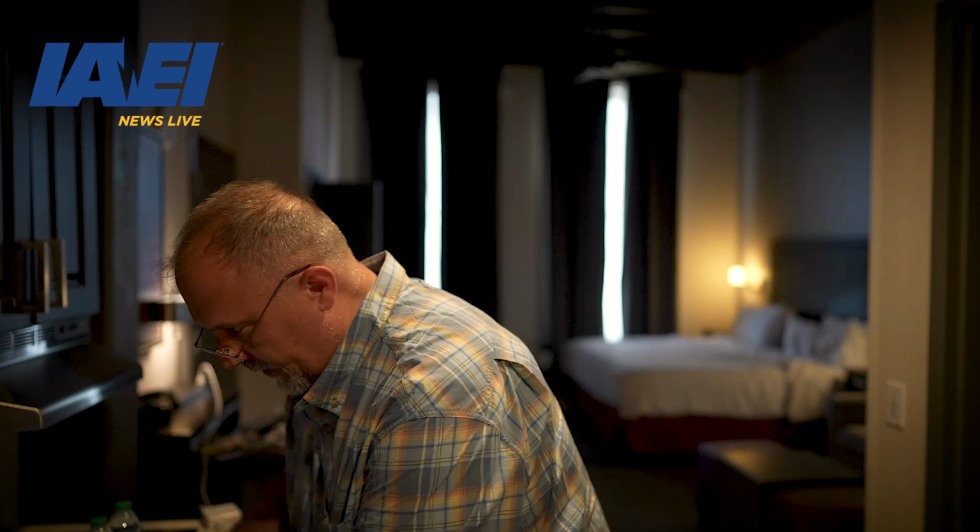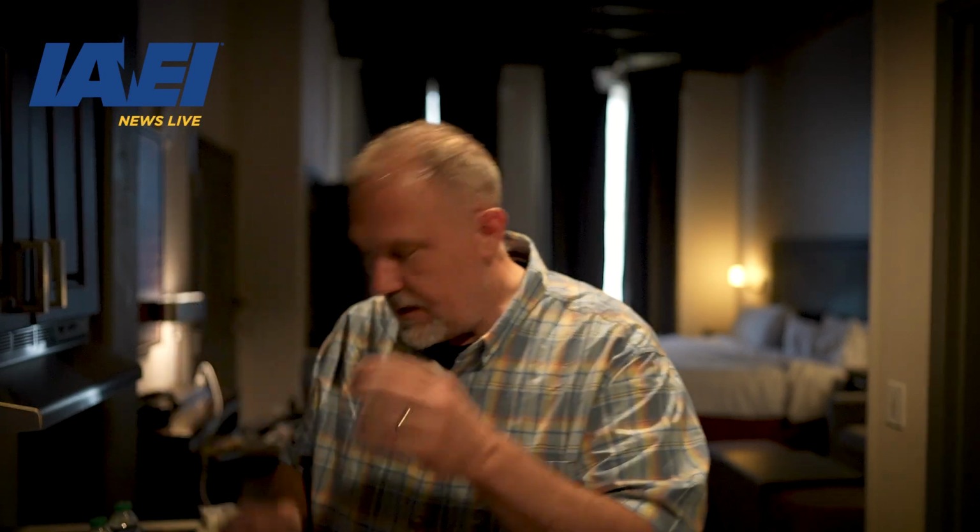All right, now. Working space. I'm going to end on this one. So when you think about your service entrance equipment, you obviously have to have it in a readily accessible location. You have to think about whoever's going to work on that equipment after the fact. So when an electrical worker shows up, you need to give them proper, ample space to do the work.